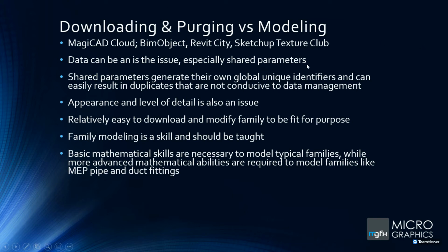So that's one example of how something within Revit, at least, plays a huge role in why you should not just download a family and throw it into a project. First, you must go and have a look at what shared parameters are in that project. Do they have the same name as the shared parameters that you're using in your project? If they do, can you replace them with the shared parameter that you need to specify? If not, can you get some other workaround?